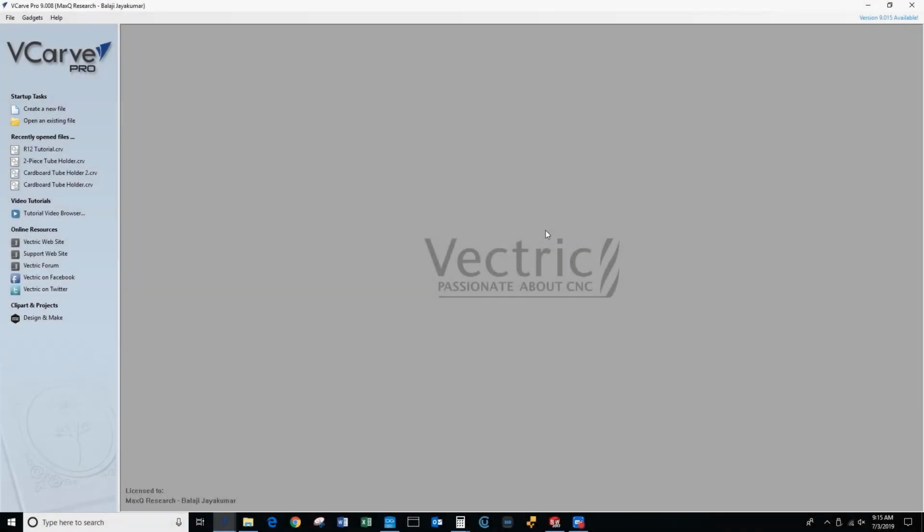Okay, welcome to this second tutorial here. In this tutorial, we're going to talk about how to take those Display Genie DXF files and convert them into TAP files. The software that we use to do that is called V-Carve Pro. In V-Carve Pro, what we're going to do first is just click right here, create a new file.